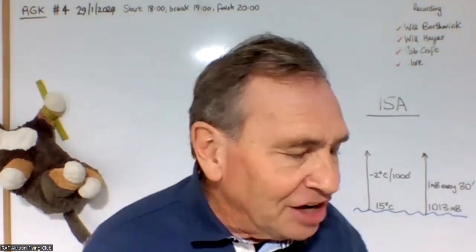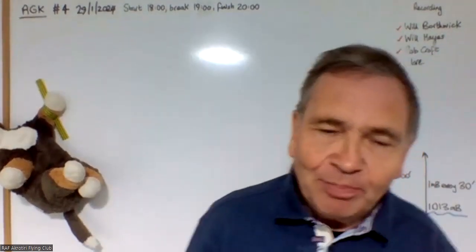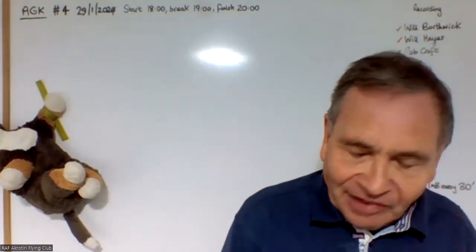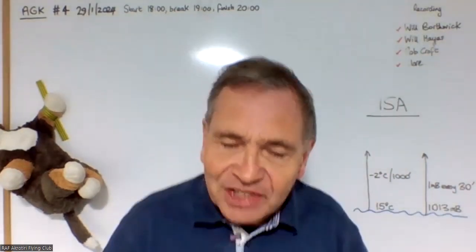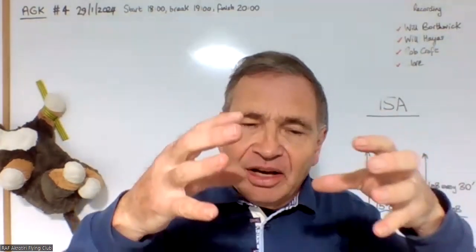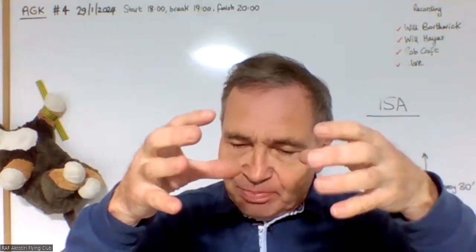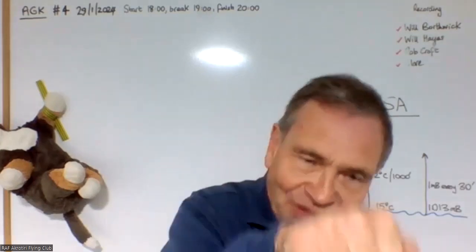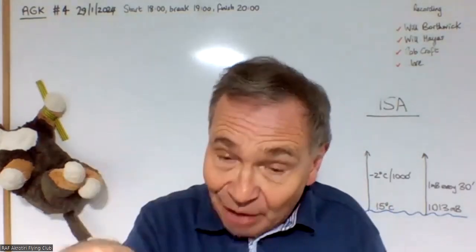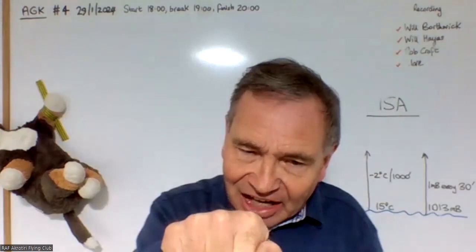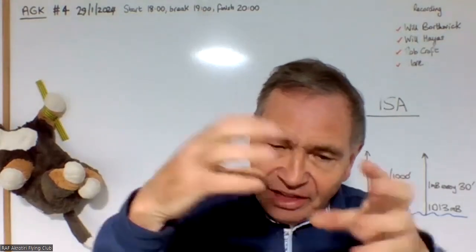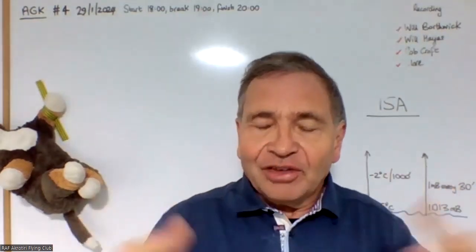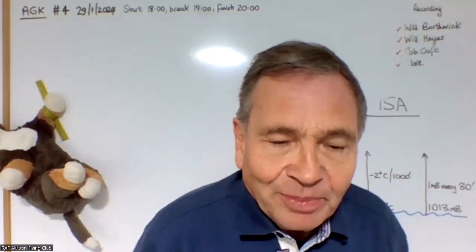So we need to generate maybe 2 or 3 pounds per square inch of compressed air. So instead of having this pump air into the cockpit, what we do is connect the tube, if you like, not to the outlet but to the inlet, and then the little air compressor on the engine is sucking the air from the cockpit.